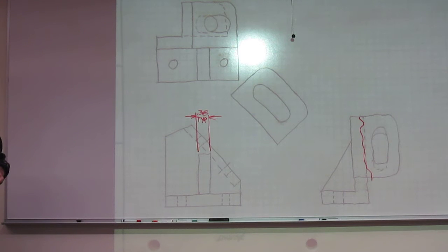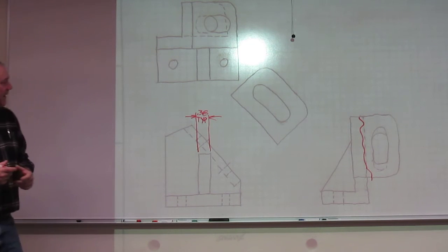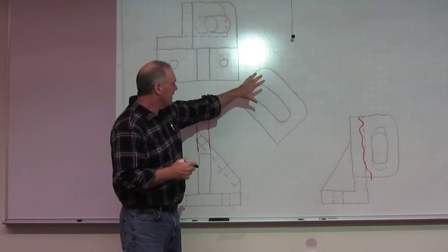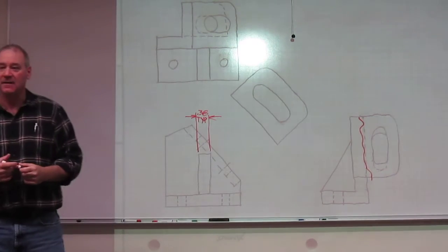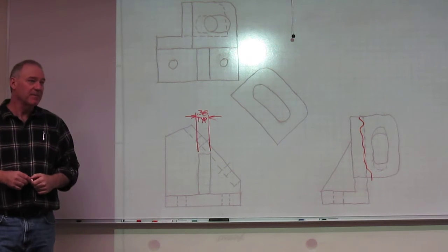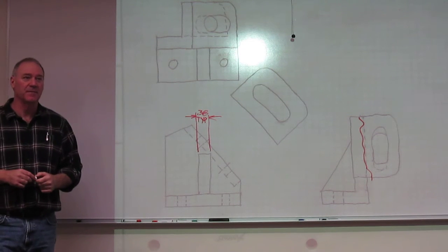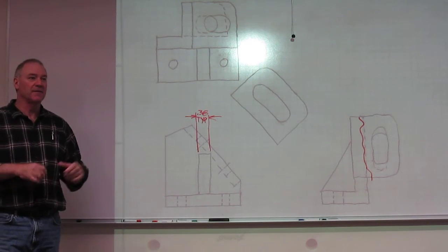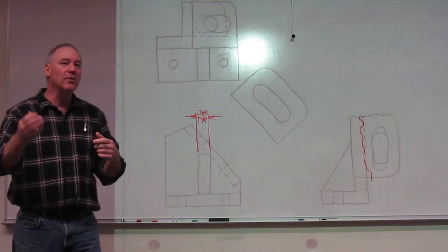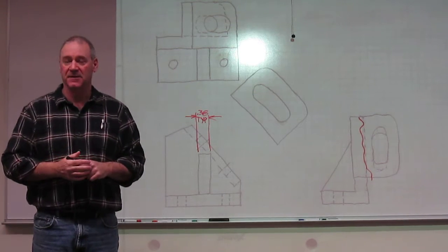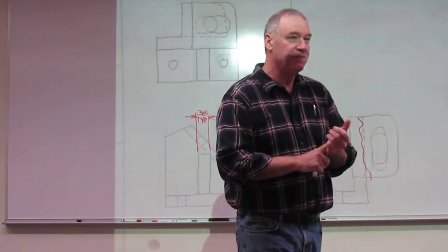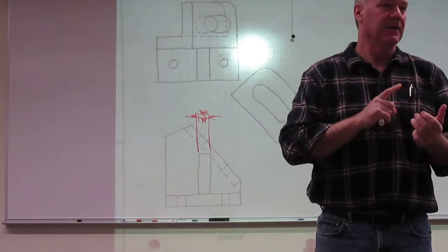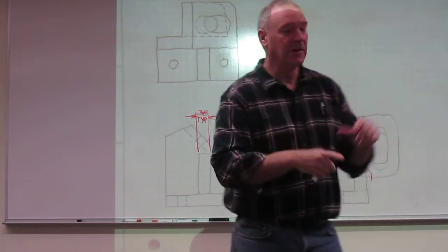Now, the reason I bring that out is because I've seen a couple of these and I don't know if they're right or wrong, in that individuals have taken this, pulled it out, and done a 2 or 3 view drawing of it. That's certainly acceptable. But you're going another step of confusion in that you're removing the rotation off of it. So you need to be doing some clarification on it. So you're either doing a removed view where you are delineating it, and I'll steal how one of the people did it.